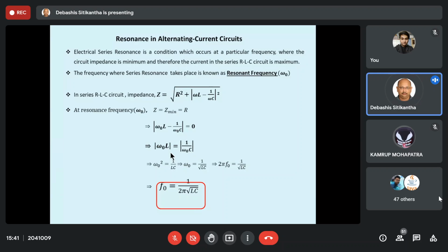Now you will see that when you are traveling at 30 kilometers per hour, some sort of vibration noise is coming from that fuel tank lid. Now you decrease the speed, and the noise will vanish. Similarly, if you increase the speed beyond 30 kilometers per hour, you will see that the vibration fades out.